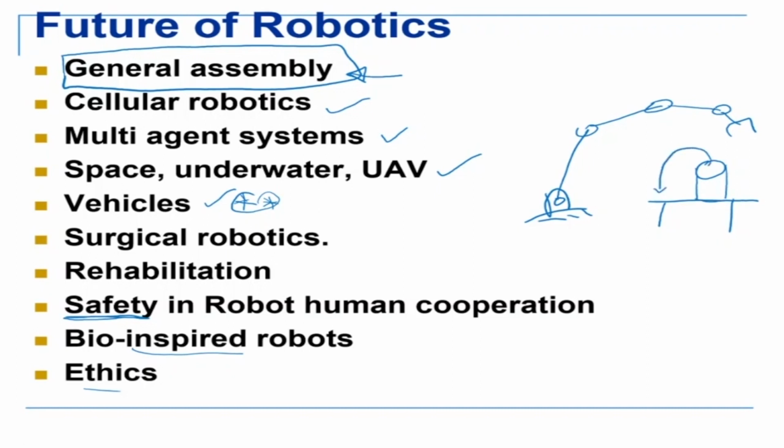What is required is points in space, because as you understand, inverse kinematics has to do with points in space. So it is following a trajectory, but these are points in space. For every point, it will do inverse kinematics, get those thetas, and then give them to the controller, and the controller will drive it there. So if you want a robot to do a task, you should be able to define points in space. When we come to robot programming, we'll see this in more detail. In the program, we define points in space, and then we use commands like move to move it around and pick and place. If you cannot define points in space, then there's no way you can use a robot.